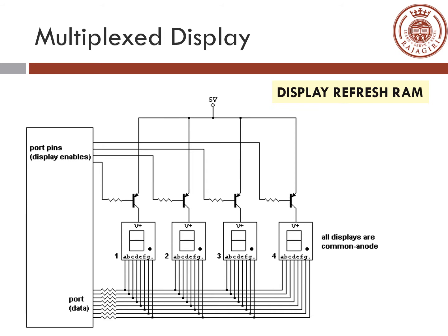And then we go back to segment number 1 again, turning off all the others. Since this is done in a sequence, in a multiplexed way, the display appears stable, showing a 4-character word to the observer.